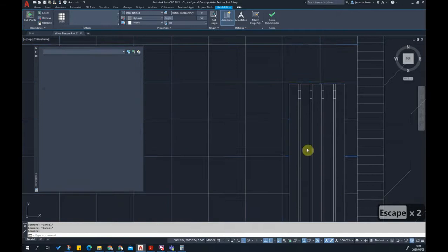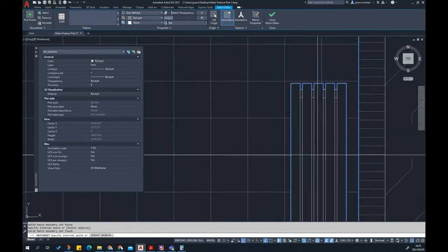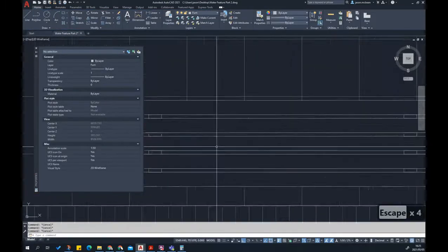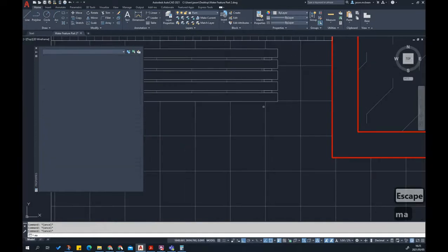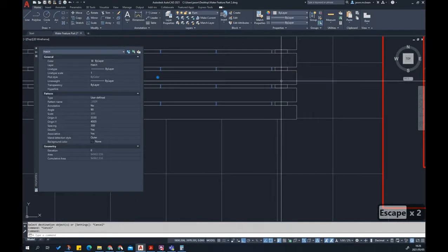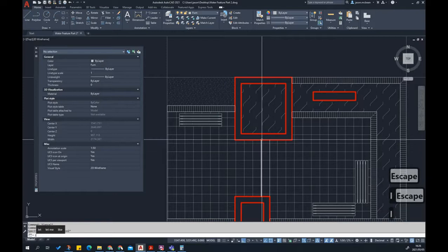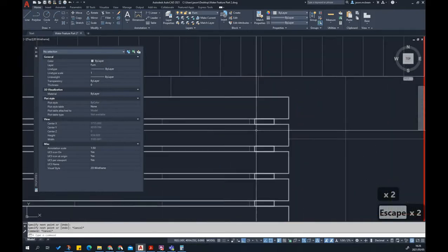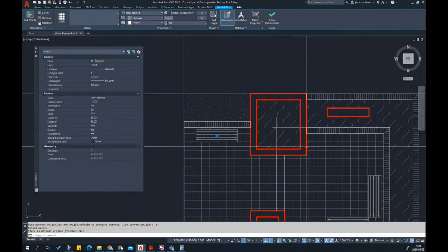Okay, with this hatch activated, we can just simply add in these little open pieces here in the middle as well. But for the sake of it, you don't really have to go through that much detail. Okay, so we can go and add those. Here's a problem here. That hatch must match that hatch. This one's origins are different. That's why. So that one we're going to have to do the same. So line. Select this hatch over here. It should all adjust. Yeah, pick origin. There we go.